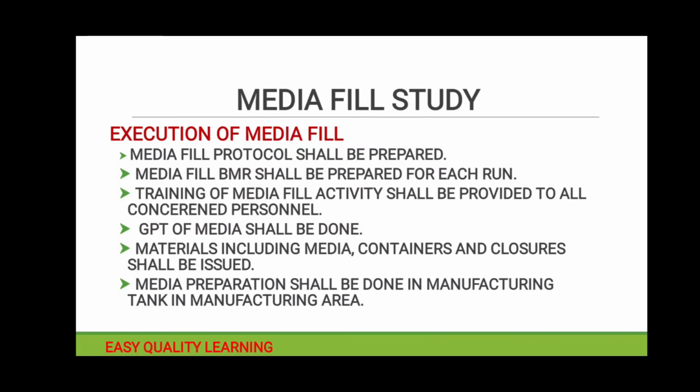Then growth promotion test of the media shall be done. Your media shall be pre-qualified, so you need to ensure that whatever media we are going to use is qualified for growth of organisms. Then materials including media, containers and closures shall be issued. As we do batch processing, whatever material issuance sequence is there needs to be followed. Media preparation shall be done in the manufacturing tank in the manufacturing area.